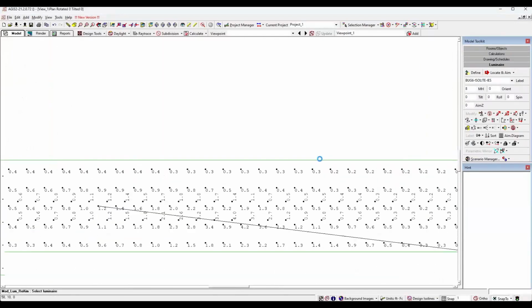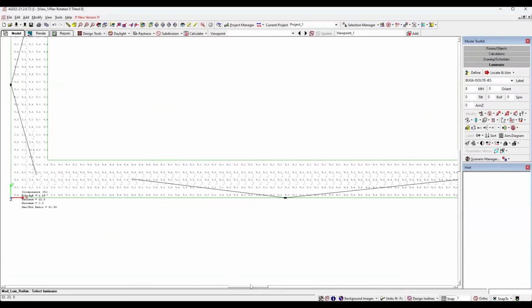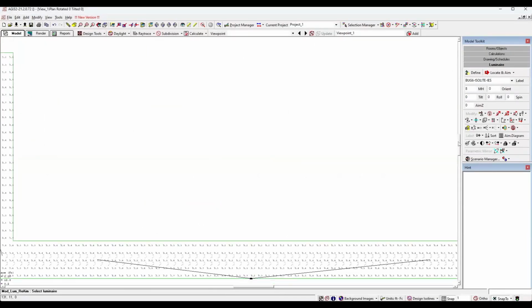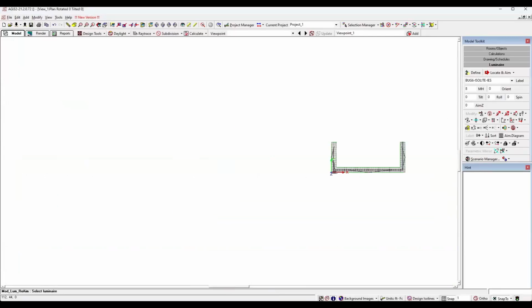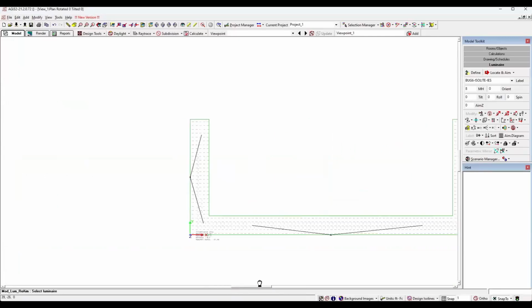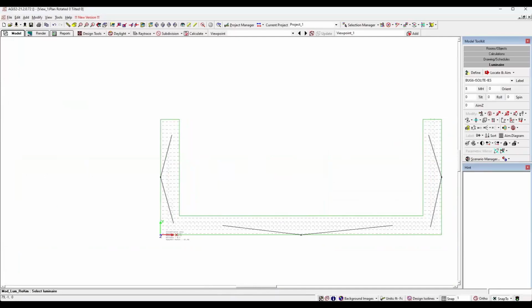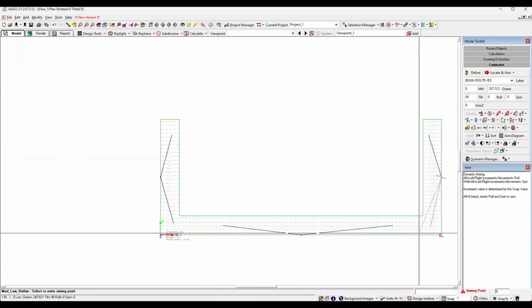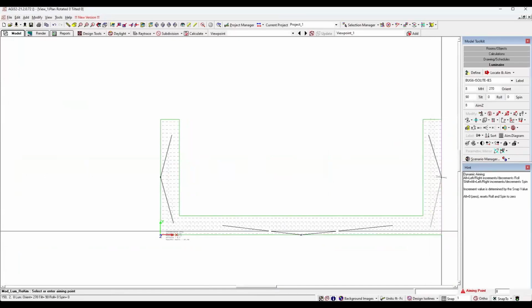Now the easiest way to handle this, if I know that the ratio is off, I'll just try to lessen the intensity of the lights. So a good way to do that would be to aim them just a little bit farther away. So I'm going to go to re-aim, and on these ones, I think these would be the problem. I can look at the points and try to dissect it, but I'm just going to try to aim this guy.